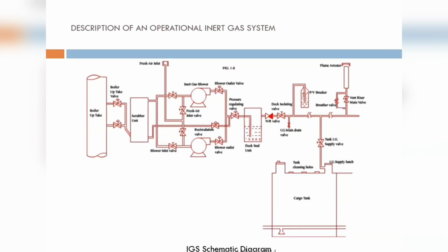Sir, in some ships I was told that the PV valve does not operate properly, so they operate it manually. They open it. What happens is in those ships, it all depends on the maintenance of the equipment. People perhaps are not maintaining these PV valves properly, not following the PMS schedule, not following the planned maintenance schedule for the PV valve. So when nobody is doing any maintenance, it will not open.